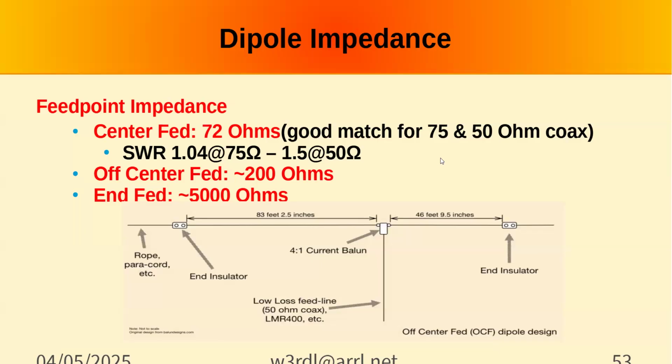Is that a measurable resistance or is it just calculated? Yeah, you stick your NanoVNA on it, and it'll tell you what it is. It'll give you R plus or minus jX. And it'll also give you just the magnitude, which is the vector value.